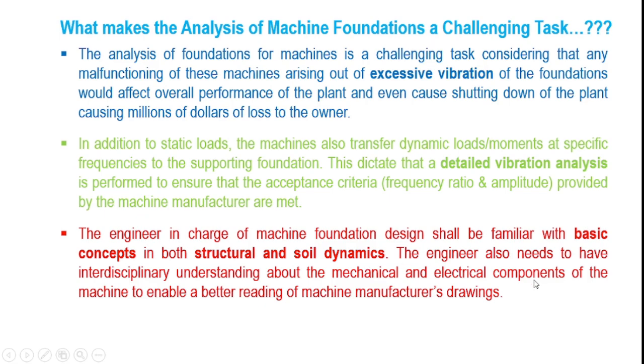Another important thing is, the basic input for any engineer who is performing a machine foundation design is a set of input drawings, and these input drawings are specifically provided by the machine manufacturer. So you must be able to read them very clearly and extract the required information.